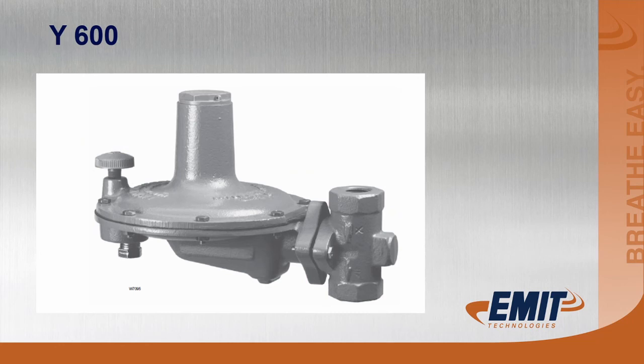Y600, very popular regulator for Caterpillar and other applications. Very robust, very reliable regulator. One of the things that's not good is the way this regulator often gets mounted. It gets mounted in the vertical position and moisture tends to build up into it. And then the regulator hangs up and doesn't control correctly. We want to take them apart and clean them and get the moisture out of them.